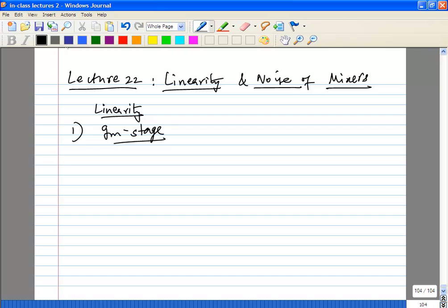You have area limitations, power limitations, and so on. And you can't use inductors. You have headroom limitations. You can't use resistors. So if you just have a simple GM stage, what can you do to improve the linearity? We know that increasing the current, increasing the overdrive, right? So that is the foolproof way of improving linearity. Okay, so that is something you can do definitely.